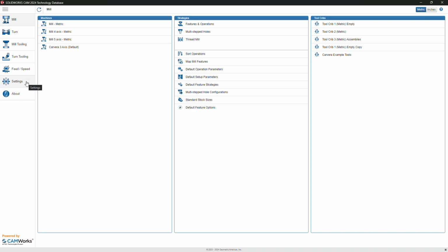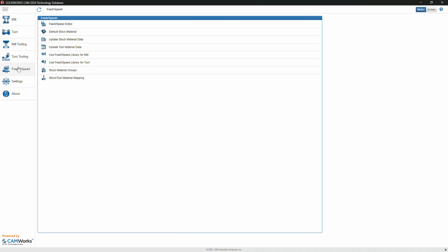We've added our tools. Now, the only other thing you might want to consider doing is feeds and speeds. So if we click feeds and speeds, we can open up our stock editors and our feed and speed editors. And I will be honest, this is not something we have time to do in this video, other than me showing you an overview, because this could be something that you spend hours doing. And if you're going to use SolidWorks CAM and you want it to be as optimal as possible, like its auto generation features, which I'll show you in the second part of this tutorial, then you really want to put in time to set up your feeds and speeds based on materials, so SolidWorks will automatically calculate these things for you. You can always override them later, and we did already create the default based on our tools, which you'll see how to do in the second half of this video tutorial.